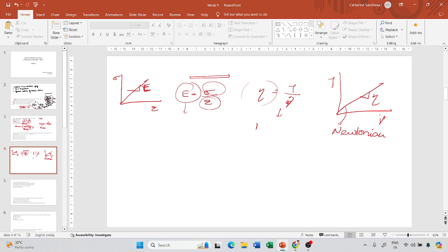And if your viscosity is independent of the shear rate only, it can evenly coat the aggregates. If it keeps changing as your shear rate changes, because the entire mixture will not have the same shear rate, since there are n number of interfaces, there are going to be n number of shear rates. Okay, so you cannot assign one specific shear rate to the material, and therefore if your viscosity keeps changing depending on the shear rate, then it cannot efficiently coat the aggregates.